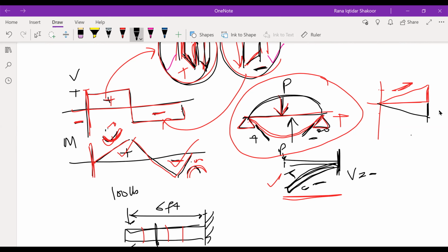Likewise, if we have a cantilever beam like this one and we apply a load P, we can see that it will come into this particular shape, right? And we know that this is basically a sad face, so it will be going in the negative direction. And whenever there is negative bending, the top surface will be in tension and the bottom surface will be in compression, right.